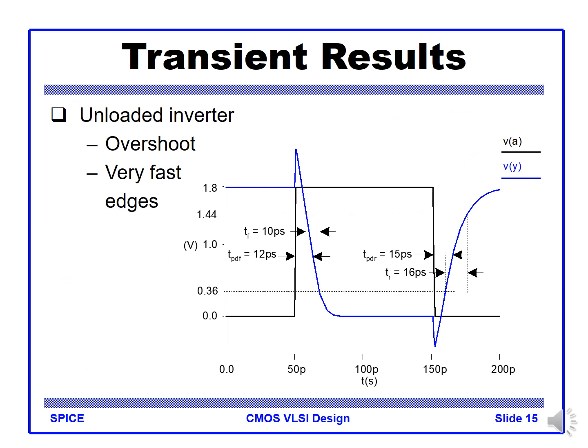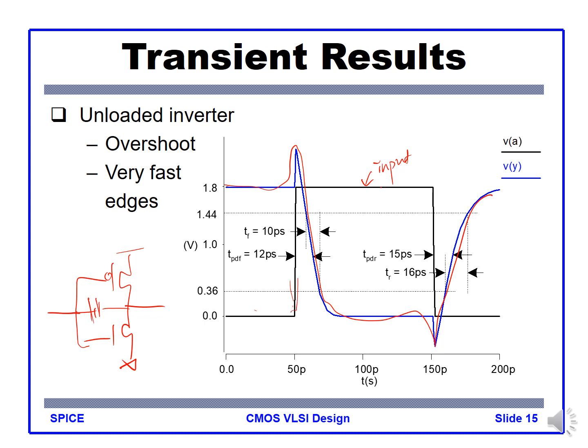At the output, you see, with this kind of pulse input, you get the overshoot like this, right? This overshoot comes from the input-output parasitic capacitance there. Because of this feed-forward capacitance, we get some of the input's sharp edge. Whenever the input changes sharply, the output will follow the input, right, momentarily. This is a very fast edge. For that case, you get this kind of glitch.